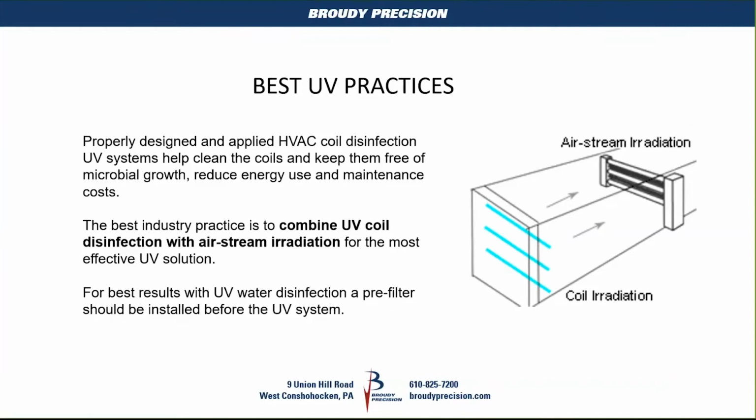They're talking here about UV water disinfection. A pre-filter should be installed before the UV system. Most of the time when I do any kind of water disinfecting, there's always a pre-filter built into those systems, and they usually come on a rack. Sometimes you see them put together, but usually they're purchased as a single unit.